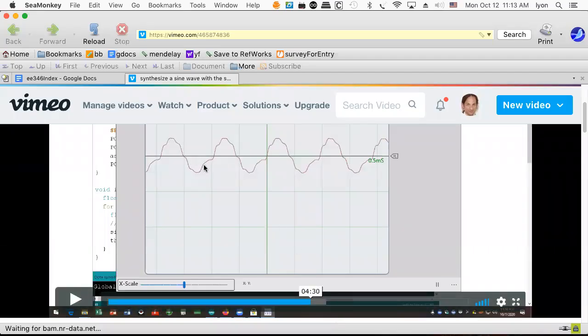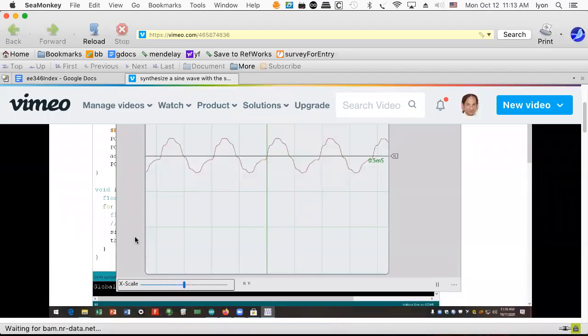Yeah, that's right. You are going to have a pulse or a step because you're skipping around in the waveform by incrementing the index register. You're not synthesizing a sine wave at a different frequency. What you're doing is jumping through the wavetable of a sine wave with different jump increments. That's not the same as resynthesizing a sine wave. So it's likely you're going to get a slightly different waveform if you're jumping from one sine wave step to the other. So maybe that's an answer.